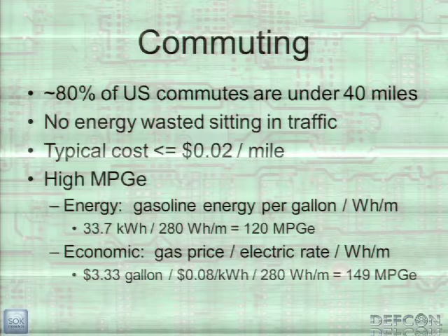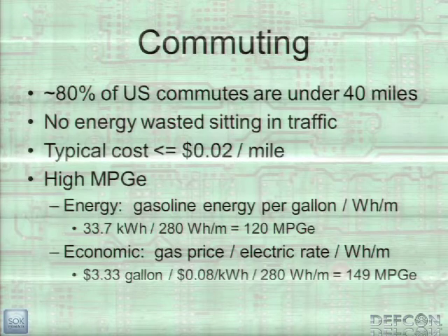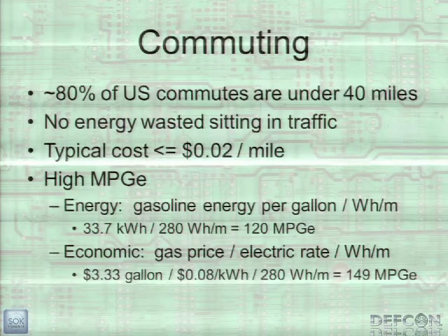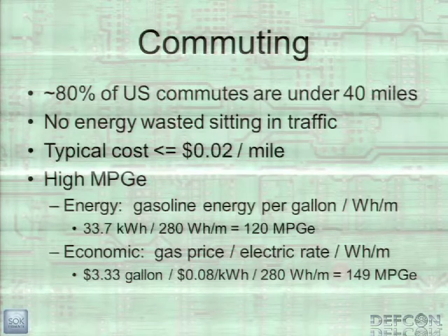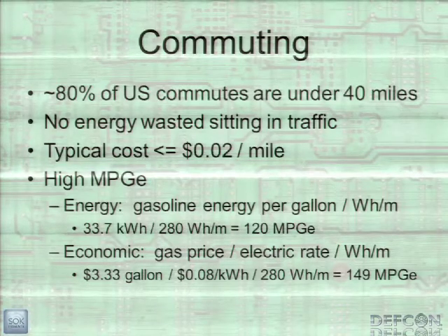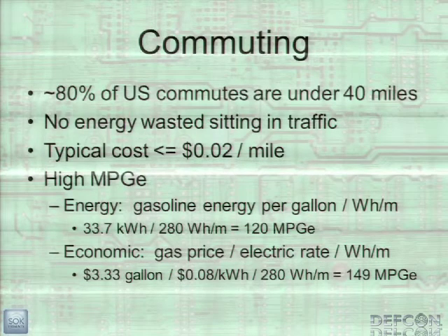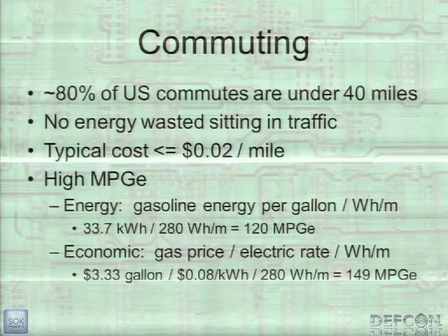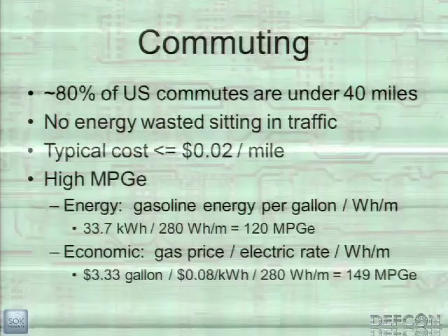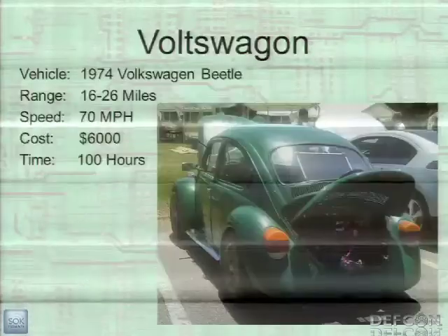For your MPGe, there are two ways to calculate that. Well, two proper ways. There are some others that the OEMs come up with. The first way is the empirical way, which is just using the energy equivalency, and based on that, my car gets 120 MPGe. The other way is to compare it with the price of gas and the price of electricity. Based on the average in my state right now, I get 150 on that. A month ago, it was over 200 compared to gas.